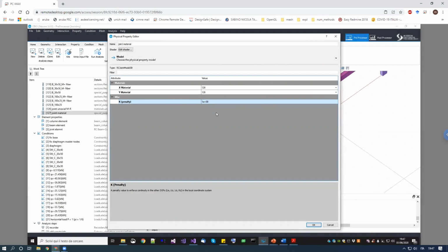Is there any criteria to locate the master node? Well, of course, it will be the center of mass. So you either need to compute it, or you can place it in the middle if it is a good approximation for you. Keep in mind that one of the main automatisms that we are creating is the one for the diaphragm. As we've seen now, in this case, you have to manually create the master node. And as Gonzalo was asking, how do you place it? So you have to find this location by hand, you have to draw it by hand, and you have to fix the remaining degrees of freedom that are not involved in the rigid diaphragm. Now, in the next version of STKO, we are going to add an automatic definition for the rigid diaphragm that will do all these steps for you, okay?